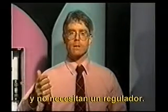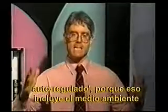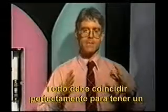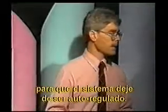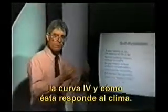I don't need a regulator. That's not true. It's real important to say a self-regulating system because that includes the environment as well as the module and battery. Everything has to be matched perfectly to have a self-regulating system. If any part of the system is not matched, you don't have a self-regulating system. The concept behind self-regulation has to do with our IV curve and how it responds to weather.